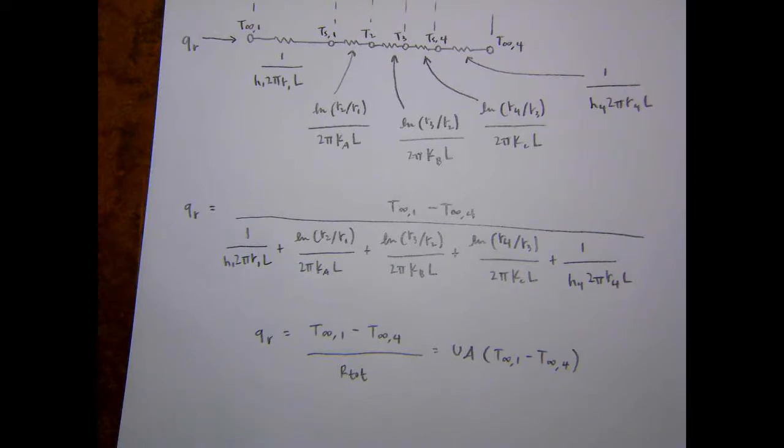That's what enables us to look at a system that is maybe just conduction through a wall, or conduction with convection on both sides, or convection on one side, or 3 different materials and convection on both sides. Those assumptions let us say that the heat transfer rate through all of those different layers of material or fluid is going to be constant. Okay, and that was what you proved in your first homework. Yeah. And that's only for materials in series, not parallel.